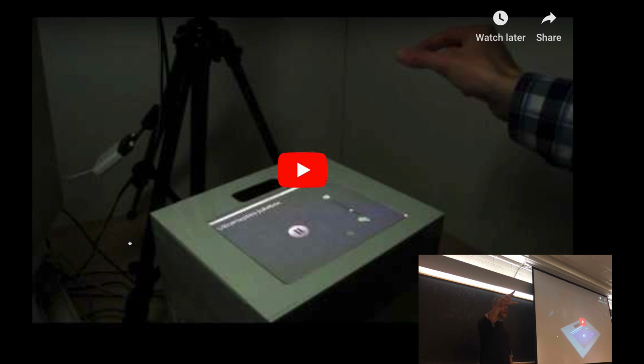How do they know where you're grasping in 3-dimensional space? Good old Leap Motion, right? So the input to this device is the 3D coordinates of the bones in the hand. The user's hand is here. Depending on what information you're trying to give to the user, the output of this machine is frequency and phase offset of these 25 ultrasonic transducers. That's the output of the machine, which becomes input to the human, which in this case is tactile input. You feel that your hand is touching something.